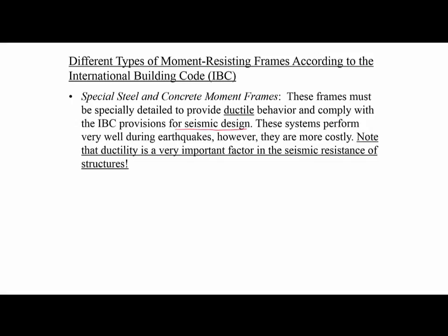Now, this ductile behavior in seismic areas is very important, and the reason is that when we design the building, generally we cannot make it earthquake proof. This means that if the earthquake is very strong, the structure may get into plastic behavior, become inelastic, and deform, but we don't want it to disintegrate.